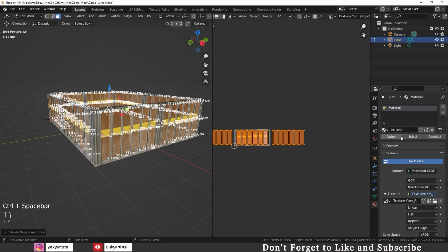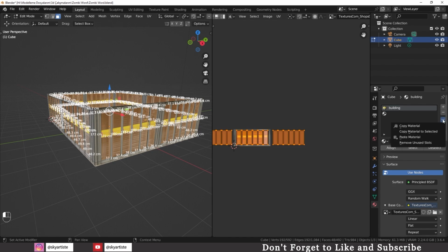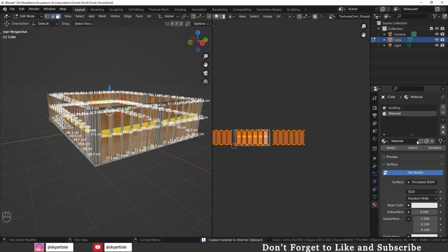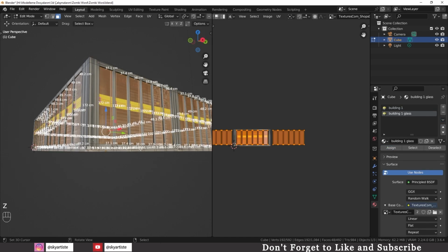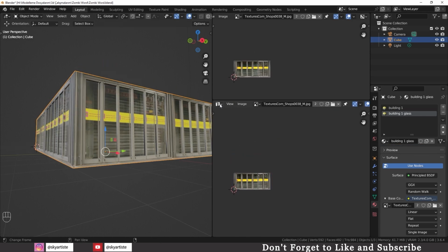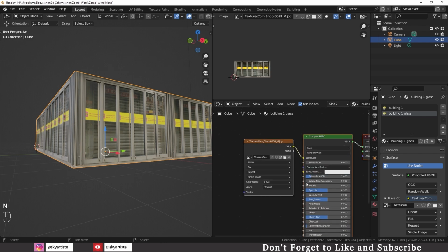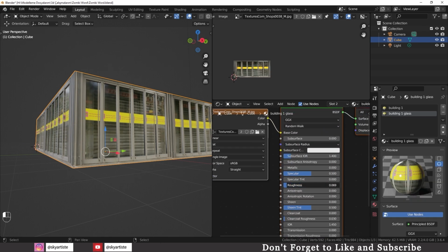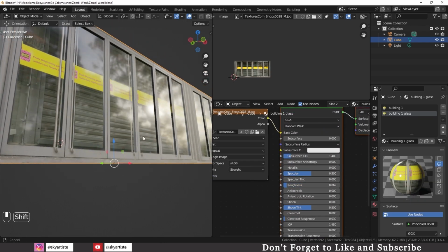You can name our materials if you wish. This way we avoid confusion. By copying the main material, we transfer the location to the material we created. We assign the selected glass surfaces to the second material. So we throw it. We open a new window and open the shader editor here. We reduce the roughness value of the window material so that we can get a smoother reflection.